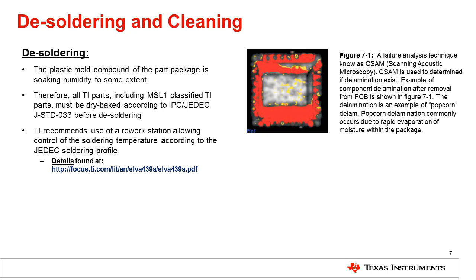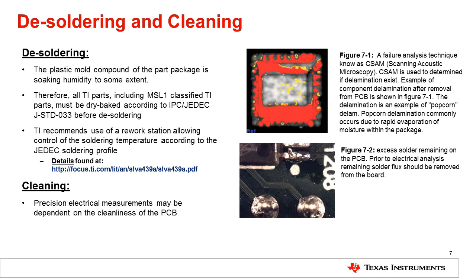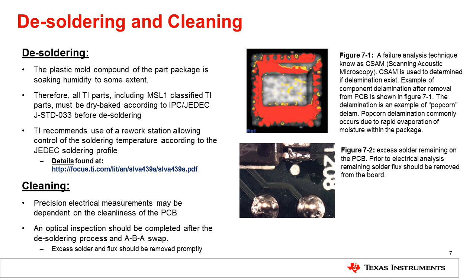Examples and recommendations of soldering controls can be found on TI.com. Details can be found using the link provided in this training. In addition, board cleanliness should be monitored during the soldering and desoldering process. Precision measurements may be affected by excess flux or board contamination, leading to skewed measurements. For example, excess solder flux shown in Figure 7-2 may impact electrical characteristics of an application, resulting in an incorrect reading from an analog to digital converter. Therefore, an optical inspection should always be completed prior to and after soldering a component.